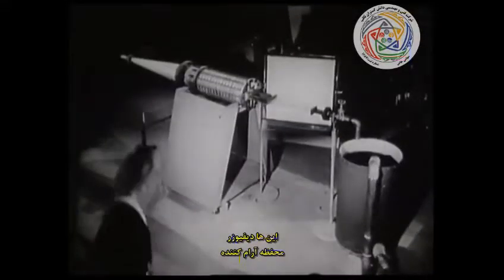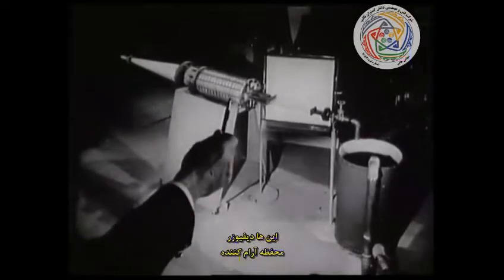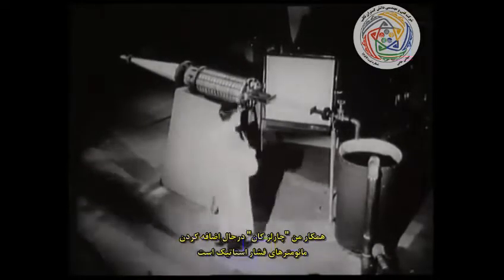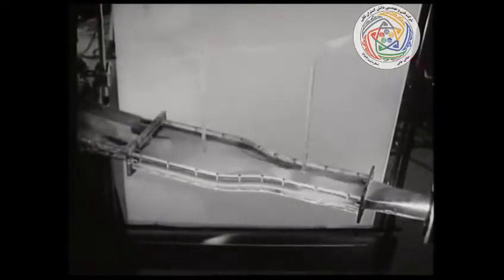Now let's look at the experiment. Here is the diffuser, the settling chamber, the nozzle, and the test section. My colleague Charles Kahn is inserting the static pressure manometers. And now he has started the flow. We see that the pressure falls from the upstream section to the downstream section. What about the velocity of the flow?